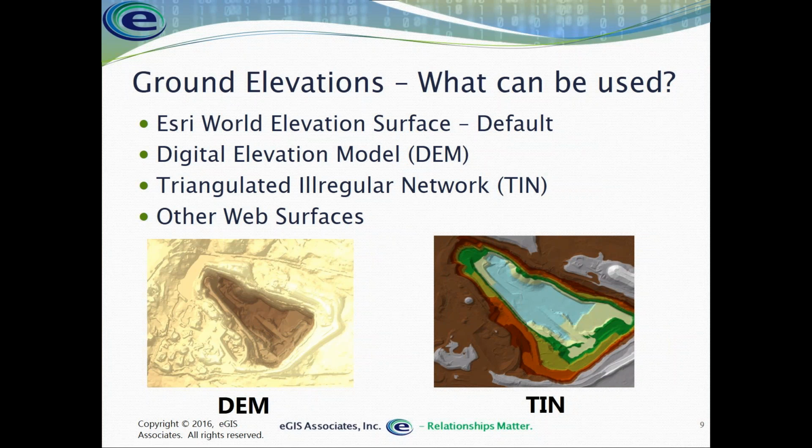They work really well, usually generated out of the Spatial Analyst extension for ArcGIS or ERDAS Imagine or something along those lines. You can also use a TIN, a triangulated irregular network. That's a vector-based elevation surface, and it uses a series of points and triangles to establish elevations. They're usually extremely accurate, very detailed in nature. You can get those created by various surveyors and various other applications like Civil 3D, for example. So you can get a lot of information out of a TIN.